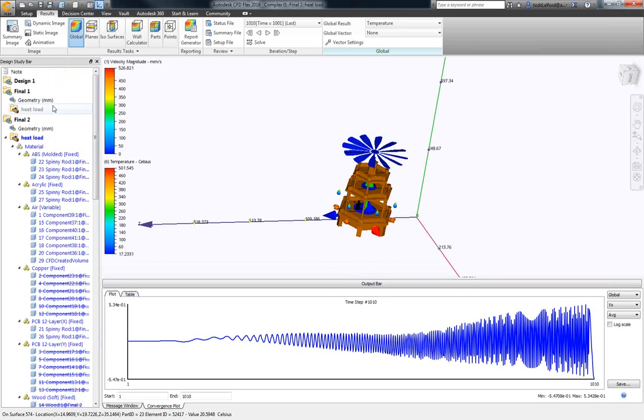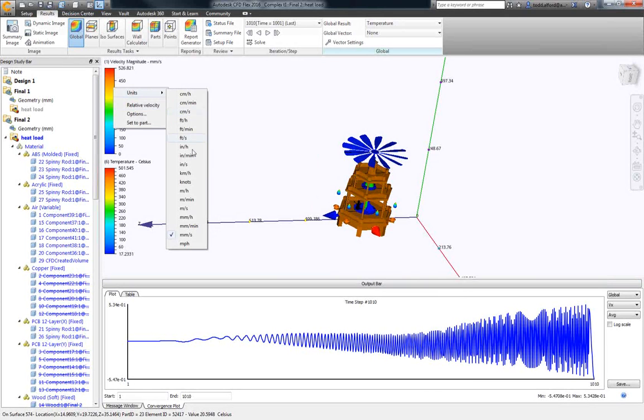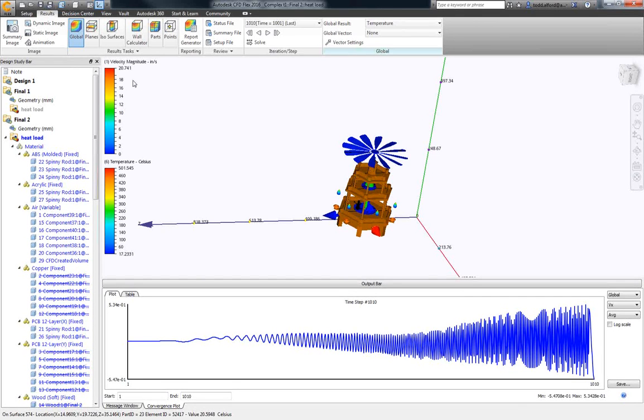And that's actually driven by your geometry units, so that's in millimeters per second. This is varying at the end by 1 millimeter per second. When I look at my overall velocity being over 500 millimeters per second, the way that I always double check that is I know natural convection analyses. Typically you're running about 20 inches per second, anywhere from really 10 to 60. So when I see that number, I feel relatively okay about it. But if that's 550 millimeters per second, 1 is going to be negligible.